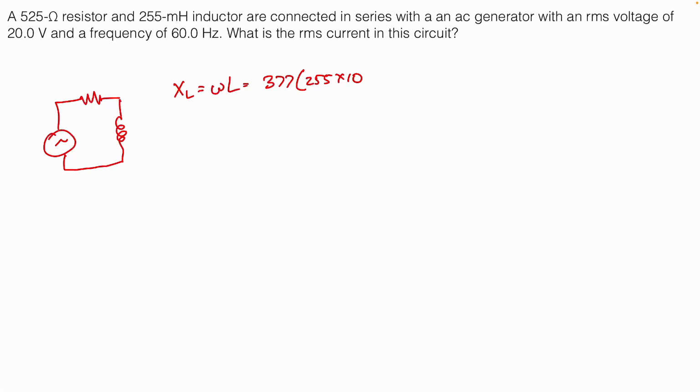And so I've used that so often in research and calculations that I stopped having to do 2 pi times f. Omega is equal to 2 pi times f, and 2 times pi times 60 is 377 radians per second. So that's why I knew that one. All right, 10 to the third, 10 to the minus third. It's a millihenry, which gets me, is anybody done yet? 96.1? 96.1 ohms, right? We just turned it into a resistor.